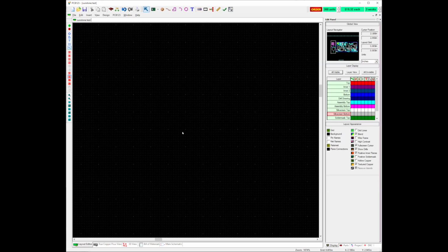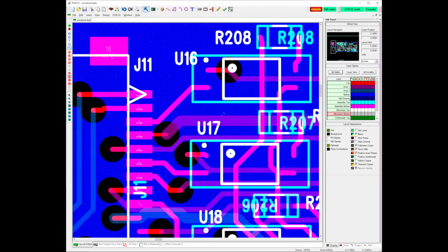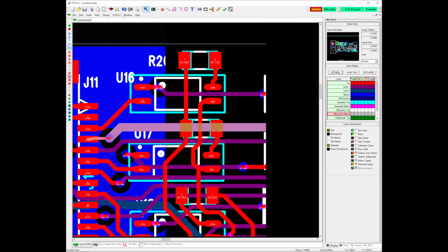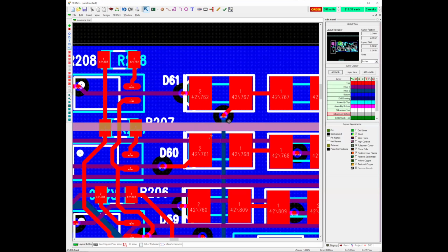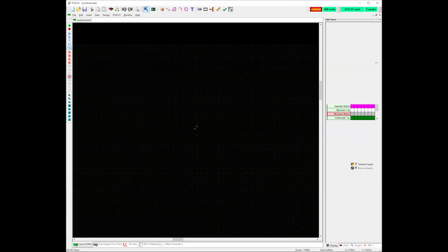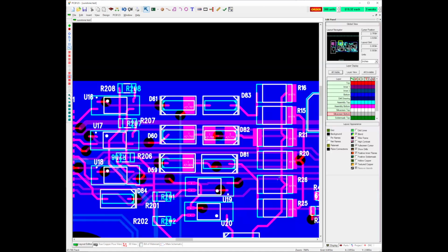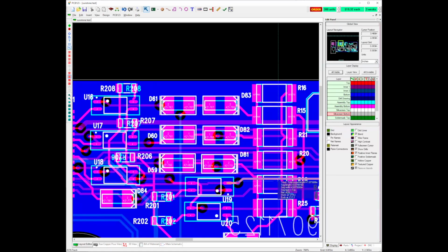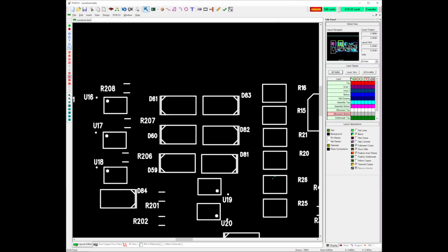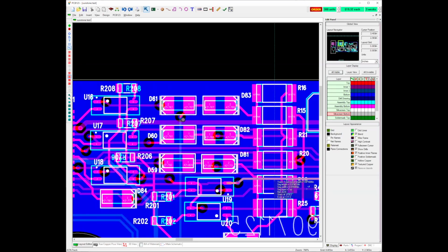and fix it. I've got a via here that's too close, and the easiest way to fix that is just to drag it up a touch. Now I've got a 30 thousandths wire that's perfectly fine, and everything's good, no problems, easy to fix. You can follow that one wire. Put it back where it was. All right.